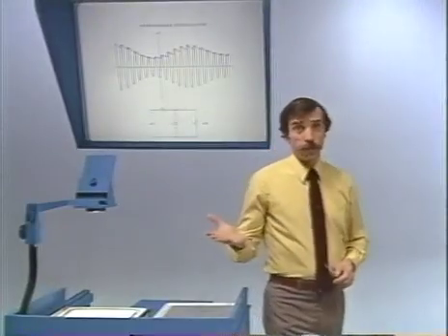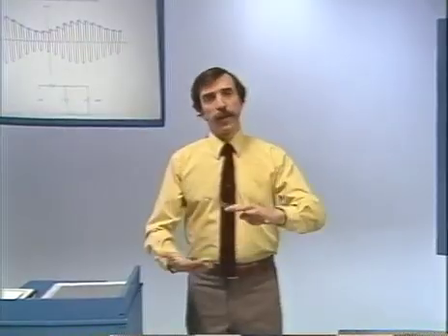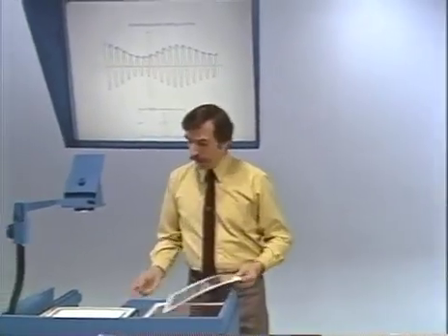Now, there's a simple solution to this. The simple solution is to make sure that the modulating signal, x of t, never goes negative. A voice signal tends to go negative, but if it does, we can simply add a constant to it, and add a large enough constant so that it always stays positive. Well, let's look at that.